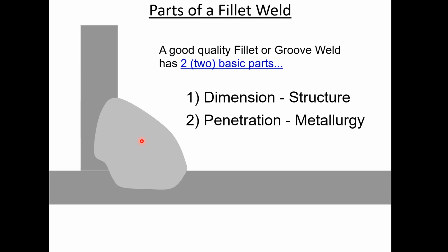So the first thing I always want you to do, and there will be more information on this later, is to make sure that when you see a wire being changed on a machine for you, that machine gets the same type of wire put back on. Whether you do it or not, you read the label. Because there are a lot of mistakes that happen because somebody goes to the crib and gets some wire, and they see MIG wire, they grab it, and they put it on, and it might be the wrong one.